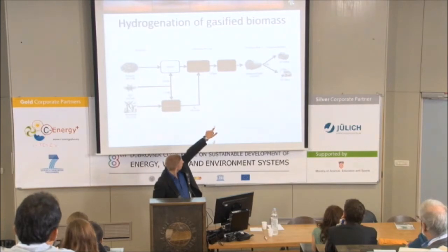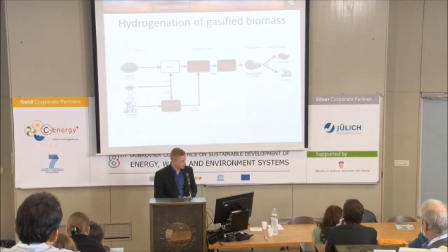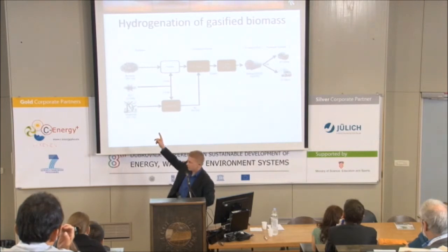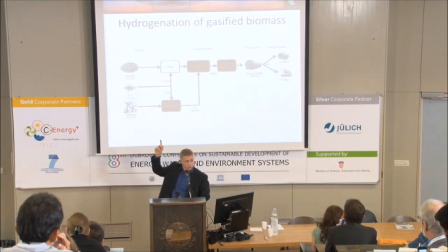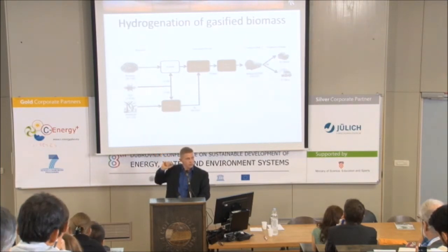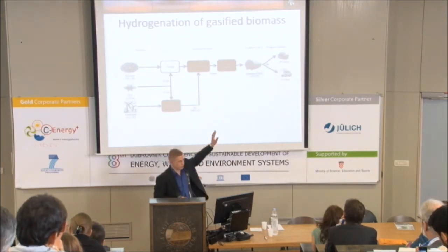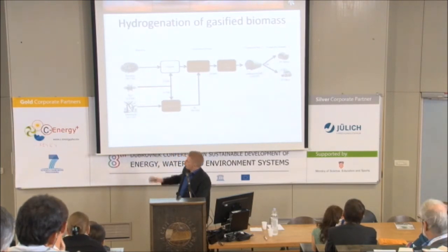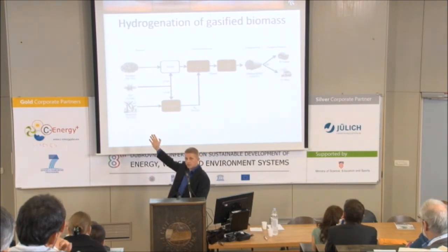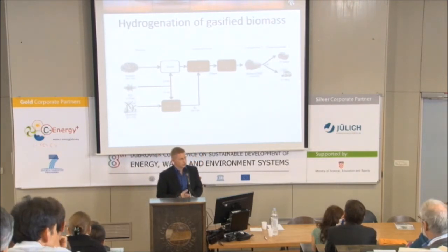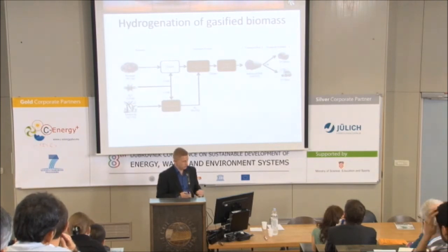What you see over here is 100 petajoules of methanol. What you see over here is 75 petajoules of biomass. And if any of you know second generation technologies, it would not be possible to have a lower biomass input than the biofuel output. So how is that possible? Well, we use quite a bit of electricity here for producing hydrogen. So we gasify the biomass, combine it with hydrogen from electrolyzers, and make chemical synthesis to create methanol.